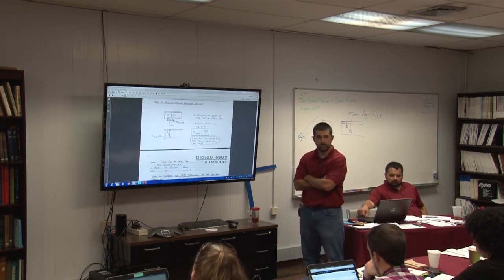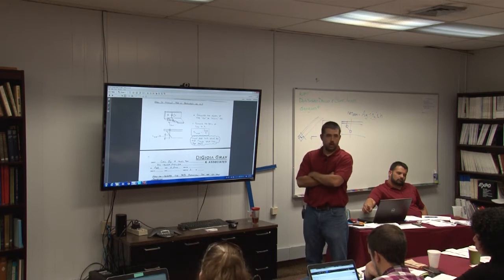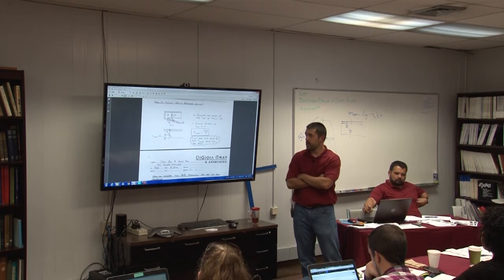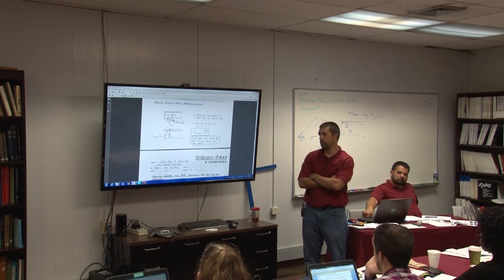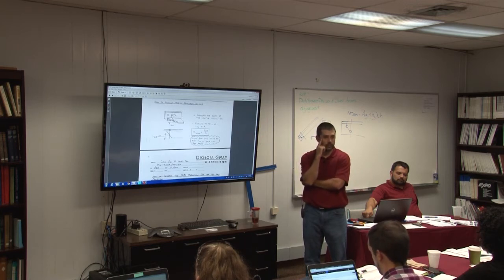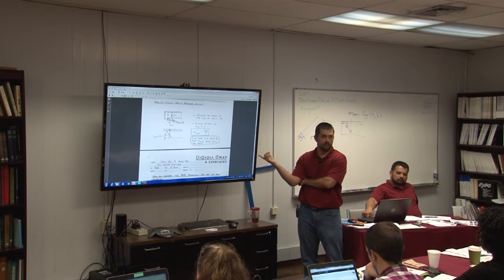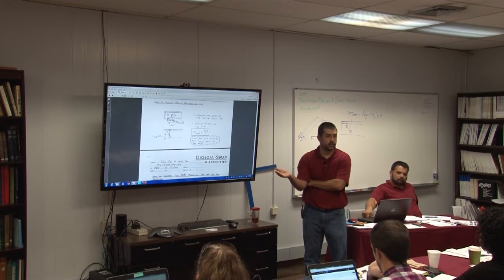I know you kind of looked at our models before, so if you can just point out which areas were the biggest areas of concern in our models. So for me, the biggest comment was, we say connections aren't modeled. And we'll get there when we talk about the rupture limit states. When you're not inputting gauge lines, spacings, or block shear values, you're omitting all of these end rupture limit states. Most every model I've seen has some value in for these net section. It's very common I see non-integer values. You don't typically see all straight integer values.